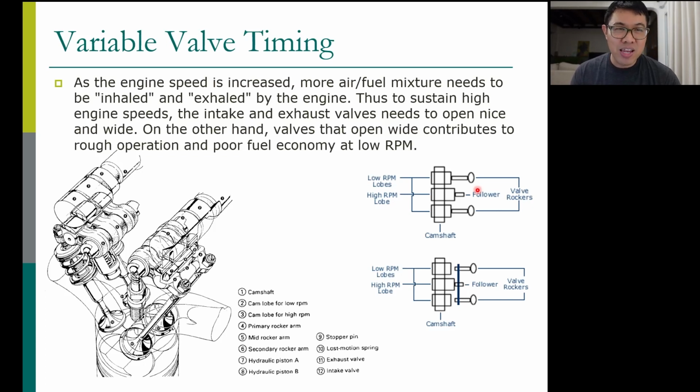Also, in every new car, I don't know, from like 5 years ago or 10 years ago, now all new cars have variable valve timing. Variable valve timing means you can adjust the valve timing for different engine operations. Basically, different engine speeds have different valve opening or valve timing.